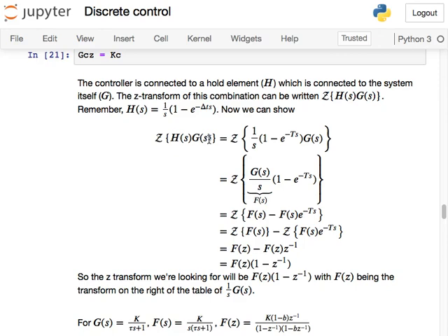I'm going to sample that signal at moments in time to get an infinite series. I'm then going to do the substitution with the Z. I'm going to find a finite representation of that, and that is how I arrive at these polynomials in Z minus 1.